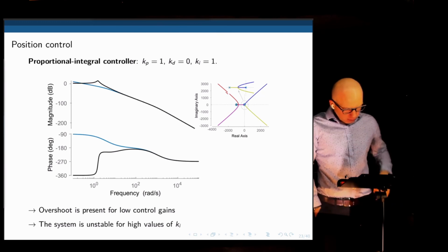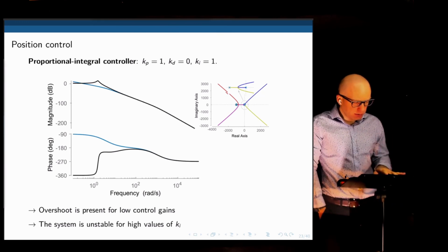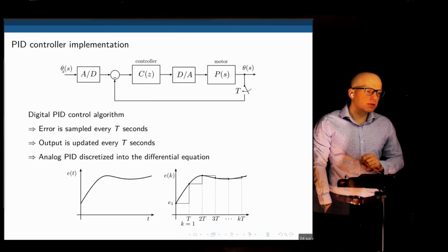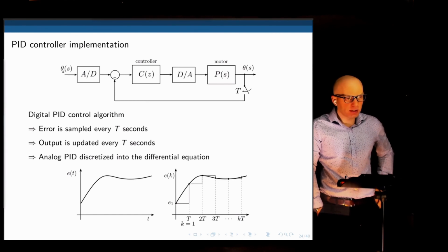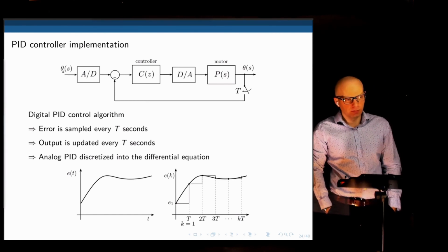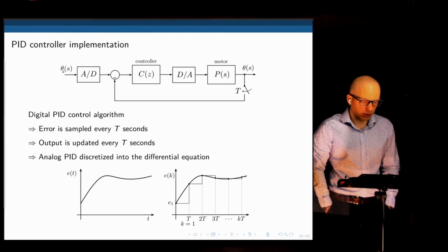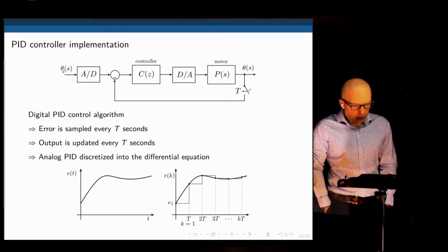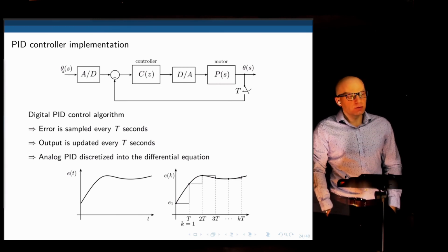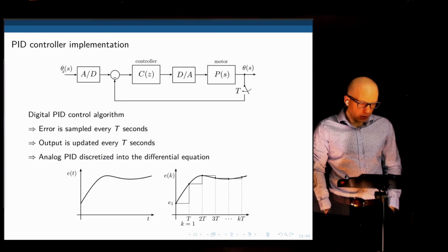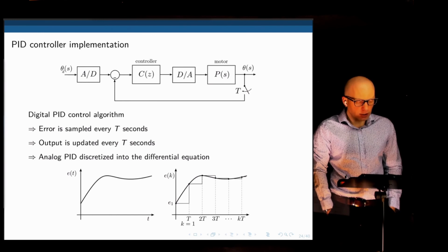Okay, so just a quick analysis to see how we use them. Now let's take this one step further and see how we implement this PID controller in a discrete version. Let's say you're using an Arduino or something like that. Here is the idea. Now the controller is a discrete function, and because it's a discrete function, instead of S, we use Z to represent a discrete variable. The motor is still a continuous function, it's P of S.